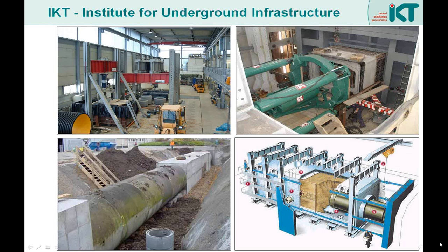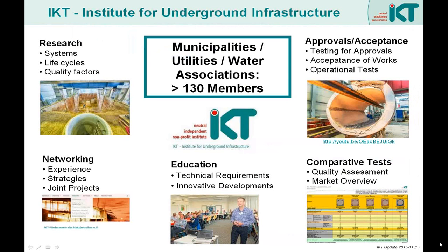That means pipe soil systems, vehicle loads, groundwater issues, and even subsurface construction processes like pipe jacking. All these can be simulated on a 1-to-1 scale in a very realistic and practical way. And we really need and use these facilities. In research projects, we look at the system behavior and life cycles.